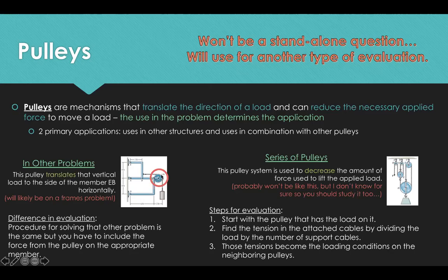I can also get rid of this pulley entirely by saying the reaction forces at the pin that holds the pulley are the load times the radius of the pulley, in the Y direction and the X direction. That's another simplification. The only thing to consider is that when you get rid of this pulley, you have to make sure this force is happening everywhere it has to happen.